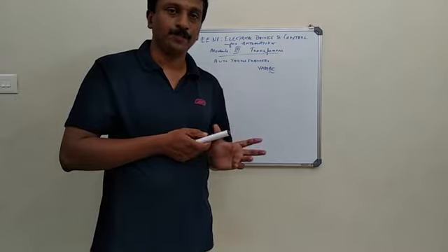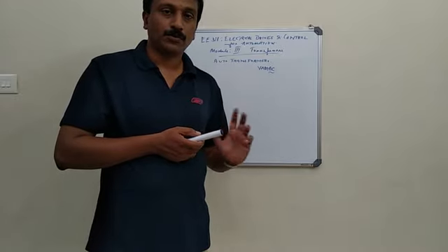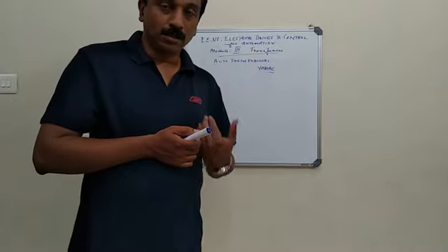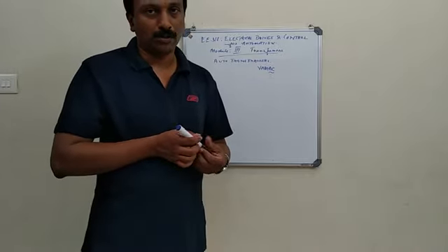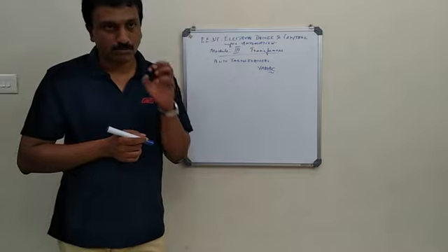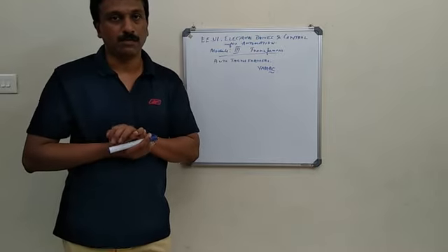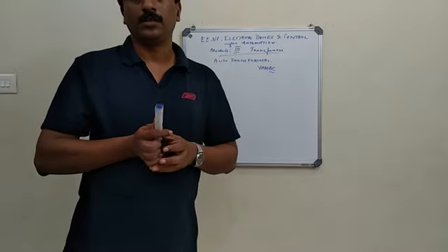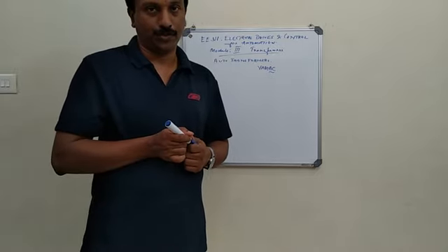And we'll see that in the case of the autotransformer, there is actually saving in copper. The amount of copper required to make a transformer for a given kVA is less for an autotransformer than for the two-winding transformer.